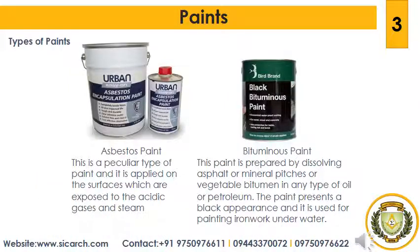So the next type of paint that we are going to see is the asbestos paint. So this is a peculiar type of paint and it is applied on the surfaces which are exposed to the acidic gases and steam. So the fourth type of paint is bituminous paint. So this paint is prepared by dissolving asphalt or mineral pitches or vegetable bitumen in any type of oil or petroleum. A variety of bituminous paints is available. The paint presents a black appearance and it is used for painting ironwork under water.